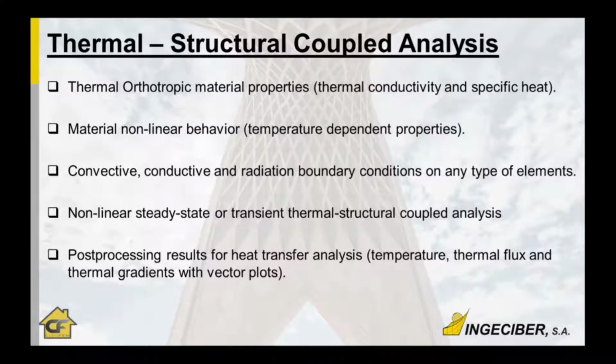For the thermal analysis, we have convective, conductive, and radiation boundary conditions on any type of the elements, and then we can perform nonlinear steady state or transient thermal structural coupled analysis. And for results, apart from the structural results we already have, we have all these post-processing heat transfer analysis results like temperature, thermal flux, thermal gradients with vector plots. Well, this is what we already have.